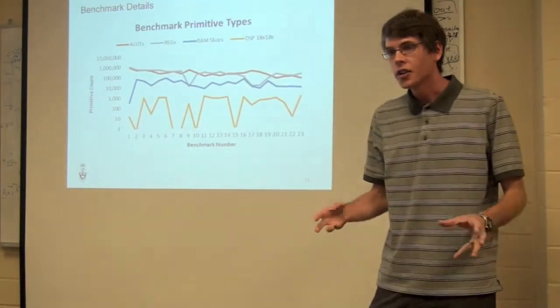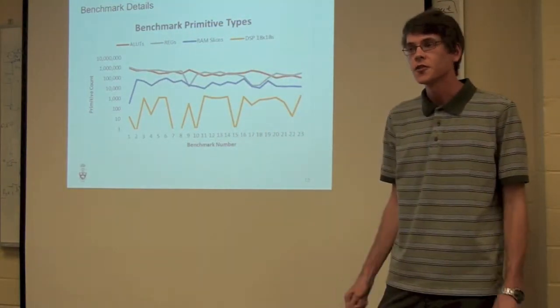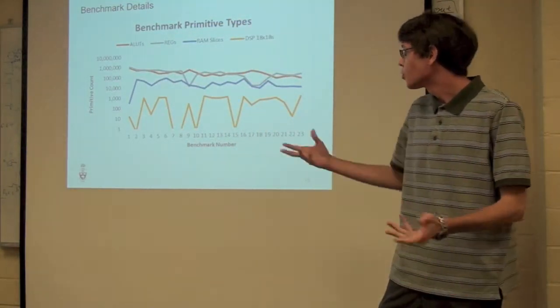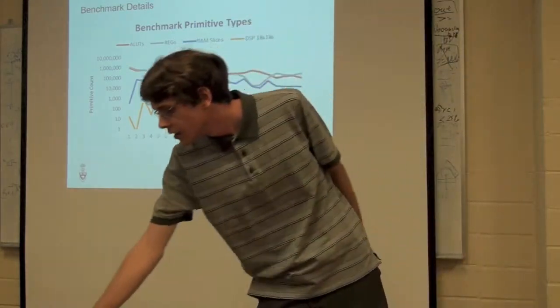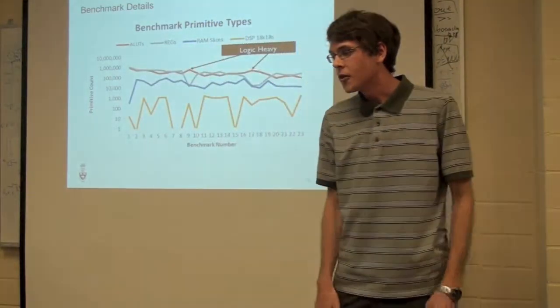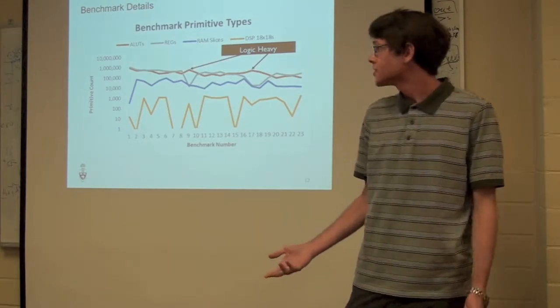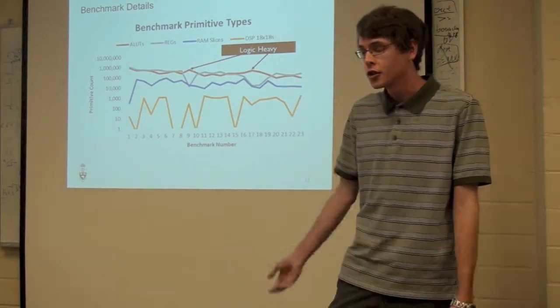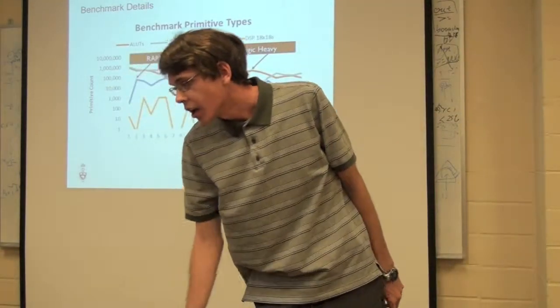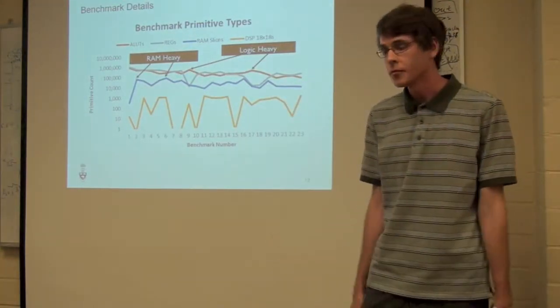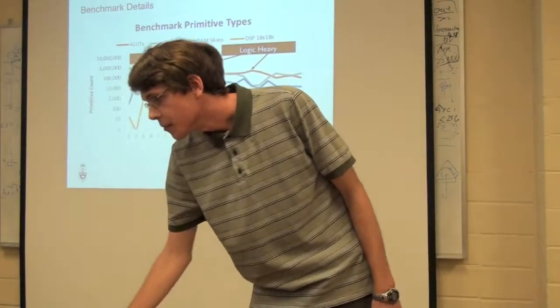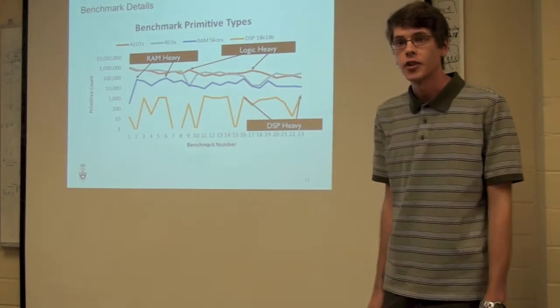We can also take a look at what the characteristics of these benchmarks are. What's the skew in terms of what primitives are used? We see that we have some good variety. We have some designs that make use of a lot of logic. We have other designs that use a lot of on-chip RAM, and other designs that make use of DSP blocks for computation.